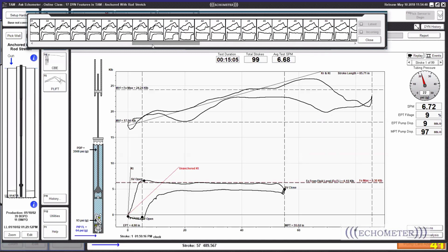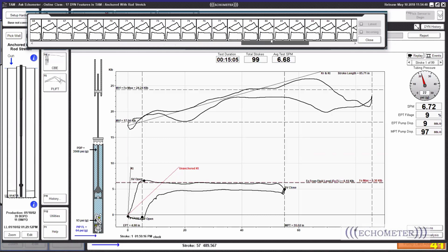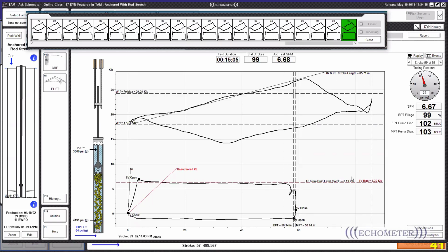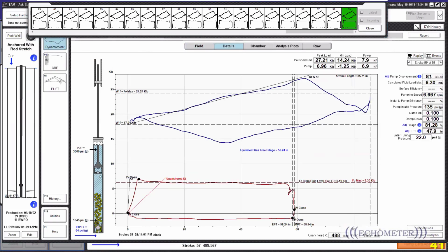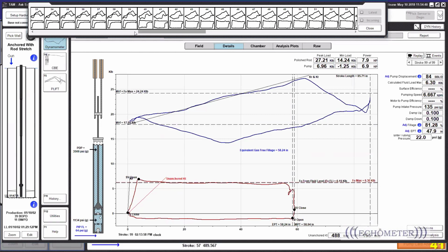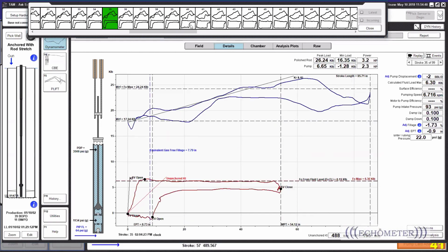And when you're troubleshooting a well, you probably need to spend more time on it. So probably if you just stick to this idea, you would say, well, my well should be producing a lot more than what it is. I should be getting like 84 barrels a day, but I'm just getting 50. So what's going on in the well? Well, the pump is not being full all the time. When you analyze the well, you see a lot of dynamometer cards with very, very low pump fillage. So this well has a kind of strange behavior. The pump is not being full all the time.